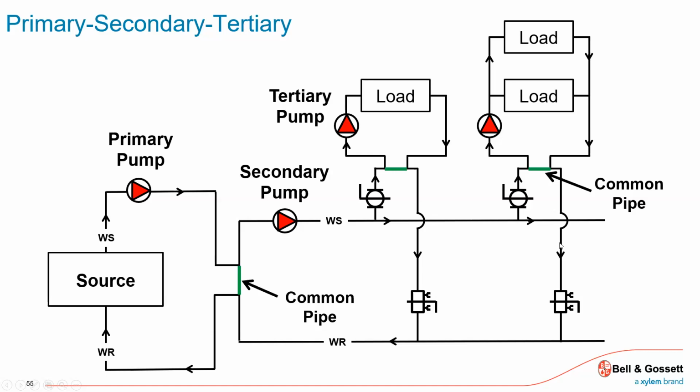Yes, sir. Yeah, exactly. That would be a distribution hot water pumps, and then that might be your individual radiation pumps going to make up air coils, going to an apartment building with 48 apartments with thermostats and a zone valve all the way up here, and you've got a variable speed, ECM pump. You could do that.